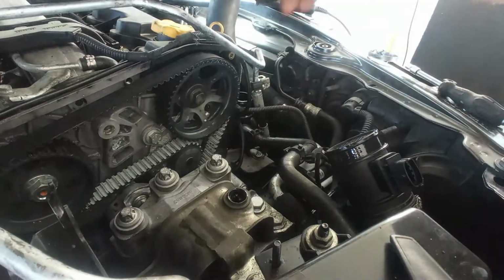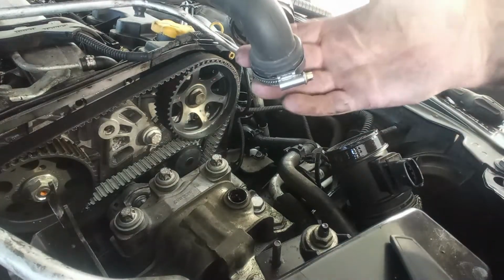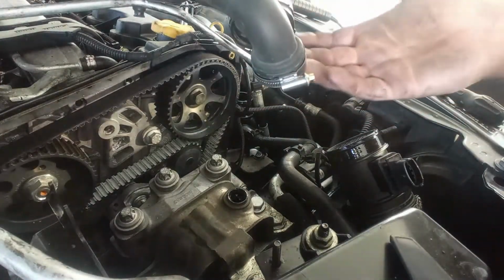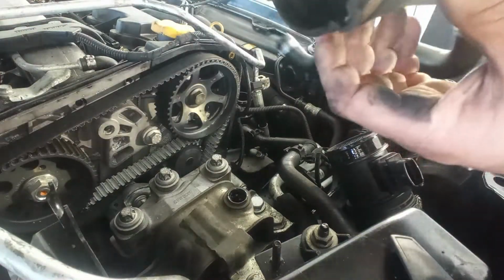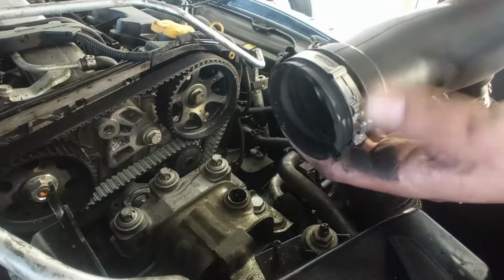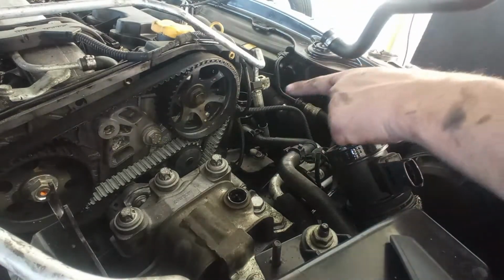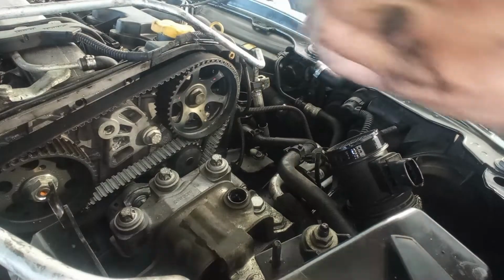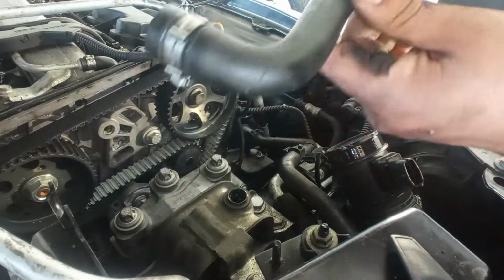Okay, so now on the airbox I put this clamp. I don't have an original one for this size, but it's better than nothing. Over here I put some tape underneath this clamp to apply a little bit more force there on the area of the turbo, not to have an oil leak over there. And here, like I told you, just a bit of tape.